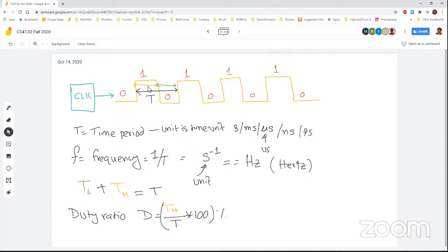And there is complex analog circuitry around this clock generator to make nice stable pulses of electrical signals, like a phase lock loop or PLL circuit. Those are really complex circuits to take the analog electrical signal coming out of the quartz element and transform it into a clean digital square waveform. That's a problem by itself, but out of our scope. Thank you, Professor.